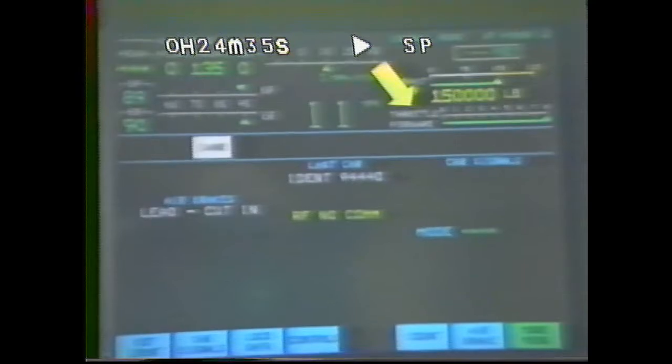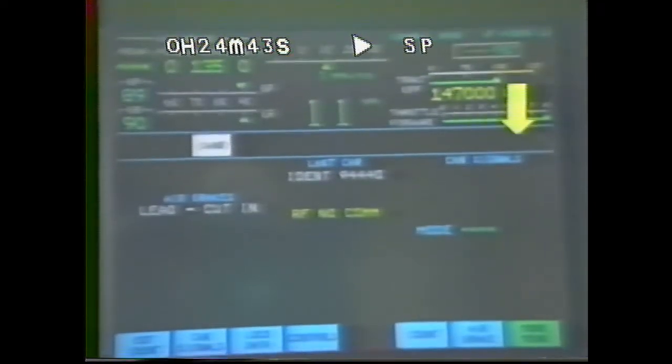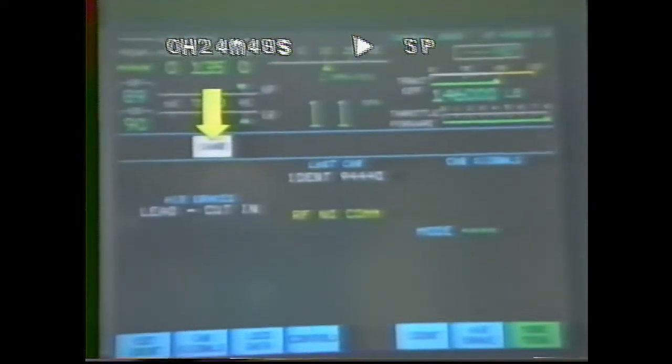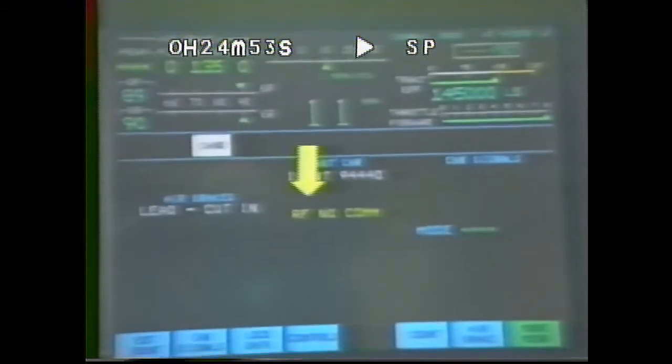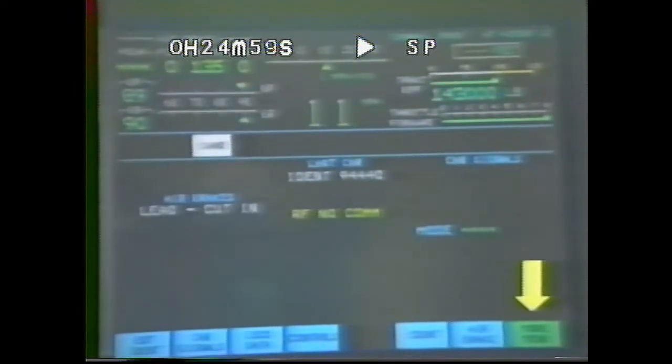The top right portion of the screen is information on power or dynamic brake amperage or tractive effort on the SD-80 MAC. Throttle or dynamic brake handle position and reverser position is also shown. The next area down is for the indicator lights, such as wheel slip, PCS, alerter and air brake fail. The next section of the screen is for locomotive status, air brake status, and crew messages. The very bottom of the screen is the menu for the function keys, or the buttons.